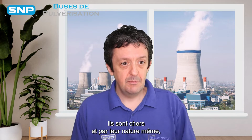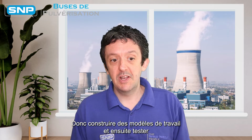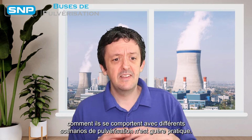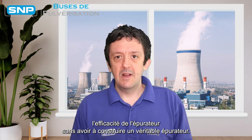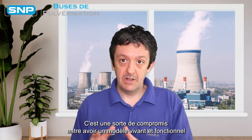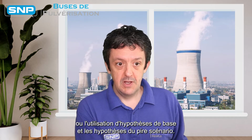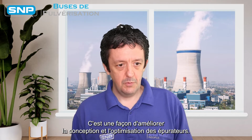It's not actually practical to run real life tests for most scrubbers. They're expensive, and by their very nature, they're hot and full of lots of pollutants. So building working models and then testing how they perform with different spray scenarios is hardly practical. So CFD is a way we can test scrubber efficiency without building an actual scrubber. It's halfway between having a live working model and using very basic, worst case scenario assumptions. This is a way that we can actually improve scrubber design and optimization.